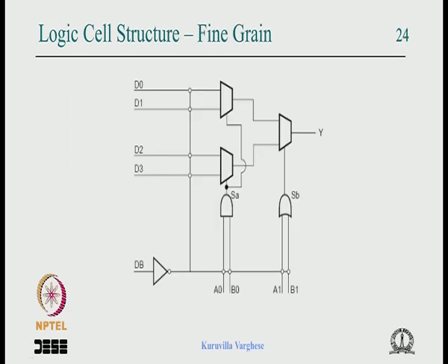And this is taken from an Actel FPGA, the Actel 54X. I should have shown that. This is taken from the Actel data sheet. You see the essential combinational circuit is a 4-to-1 multiplexer. You know that the multiplexer is nothing but an AND-OR circuit, and if you want to implement a Boolean function, it is possible.